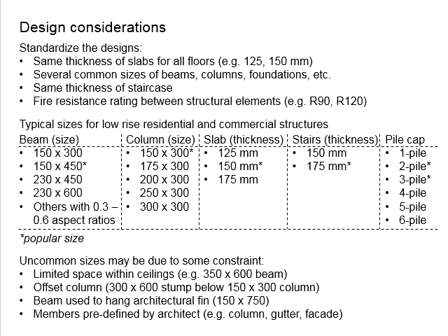Next, you will need to be mindful of the offset column. Because of the offset column, sometimes you will come to a situation where you might need an extremely large stump in order to support the beam, and then for the column to penetrate going up the floor plan, the size of the column reduces, providing the space for the offset distance.